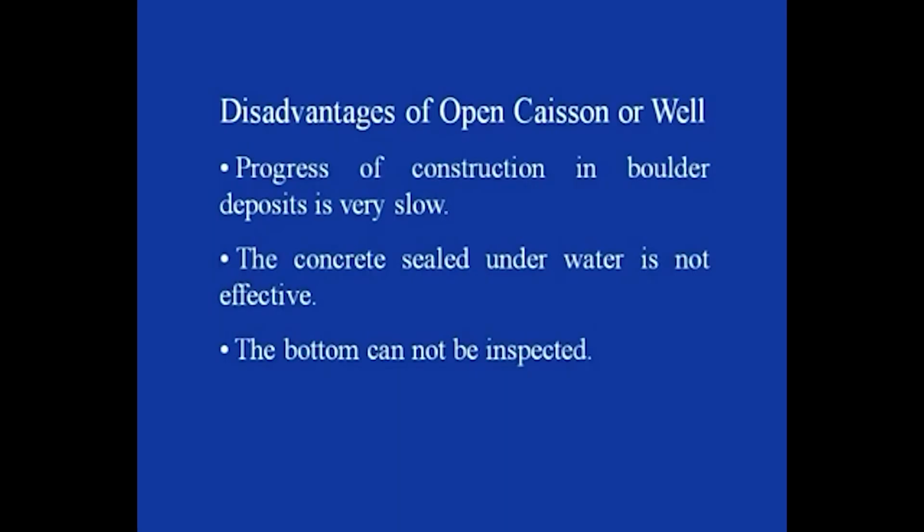Some of the disadvantages associated with open wells are that the progress of construction in boulder soil deposits is very slow. Usually wherever these well foundations are provided, we encounter bouldery strata. In case of open wells, the construction in such a stratum is quite slow, so this is one of the main disadvantages of open wells.